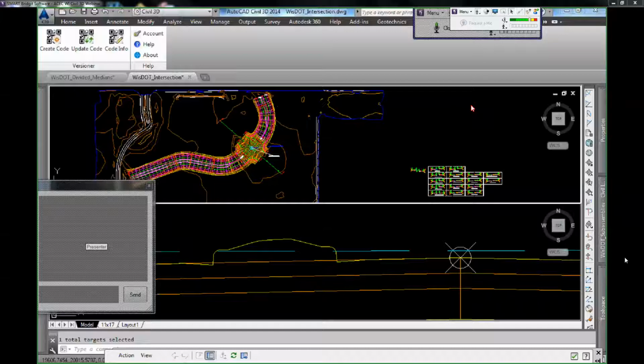We developed our library before axis of rotation functionality existed in Civil 3D subassemblies. So we don't have that functionality built into our subassemblies. The superelevation comes off the baseline alignment, and all the subassemblies that use superelevation for that alignment should either be all Wisconsin DOT or all Autodesk. It's because the Wisconsin DOT subassemblies are not built for the axis of rotation controls. Okay. Good to know.